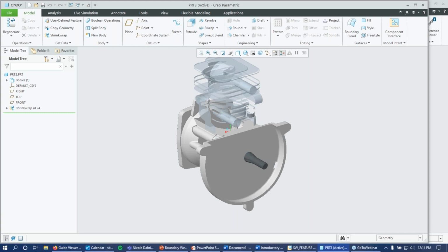But my first reaction there is yes, the shrink wrap file does have to be saved as a part. As far as parameters exported with it, yes. I don't know that I can say I've tried that with a part with just a shrink wrap in it, but I see absolutely no reason why parameters wouldn't be included with that. Essentially, it will work like a part file, and as a result, I can't imagine there would be any problems with that.